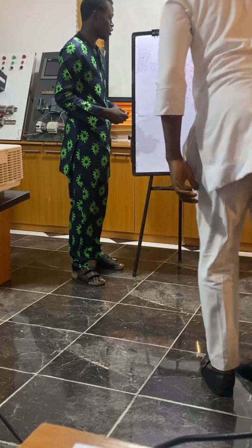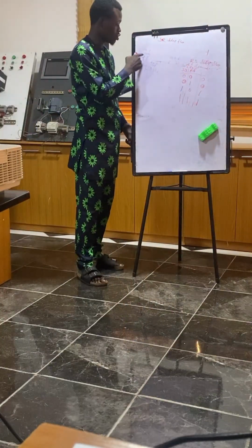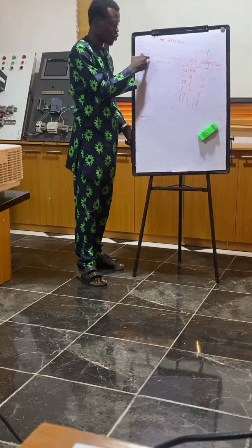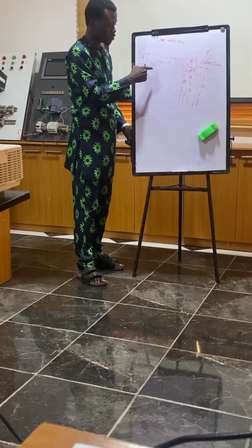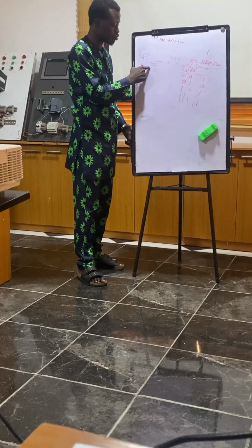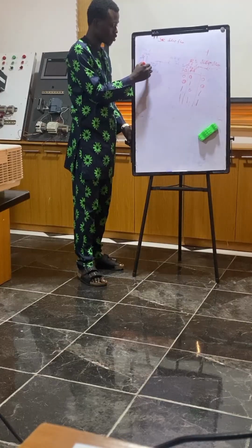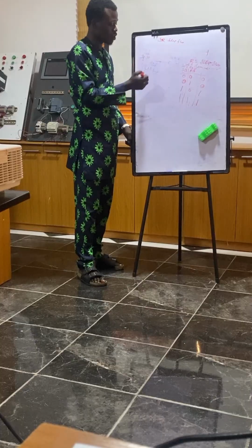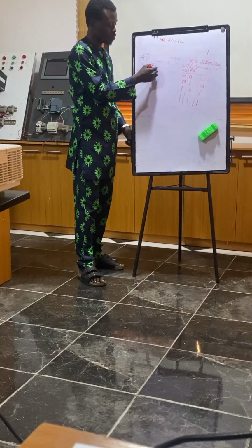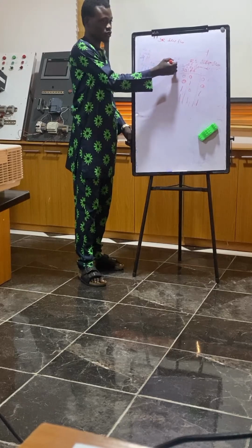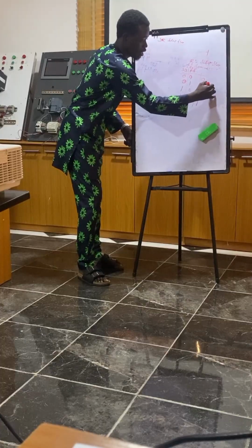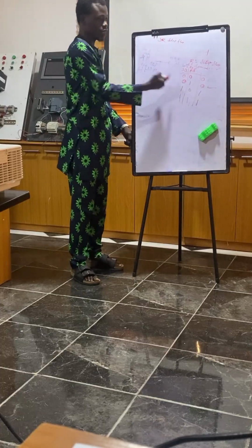Okay, the next one is we want to consider a situation where the set bit is not pressed, but the reset, which is the stop, is pressed. So this is not pressed, so of course you still have 0 at this point. This is pressed. This will invert to 0. So 0, 0 will still give you a 0 at the end. So this also confirms this other line. Okay, then let's go to the third one.